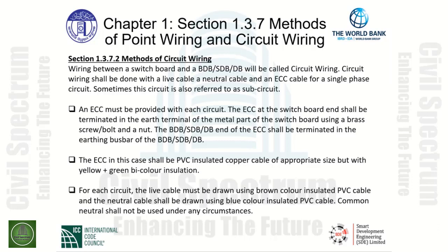An ECC must be provided within each circuit, running with each circuit. The ECC at the switchboard end shall be terminated in the earth terminal of the metal part of the switchboard using a brass screw, bolt, and a nut. The BDB, SDB, and DB end of the ECC shall be terminated in the earthing bus bar of the BDB, SDB, and DB.